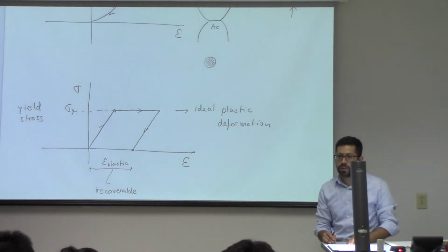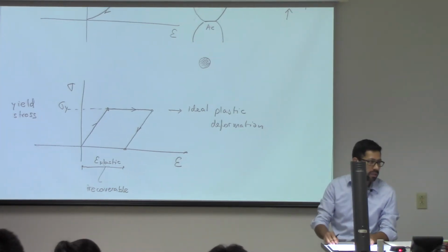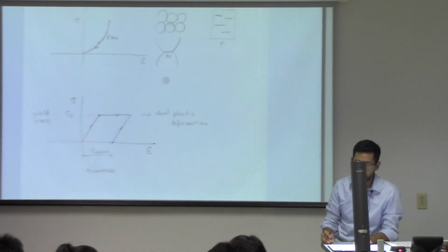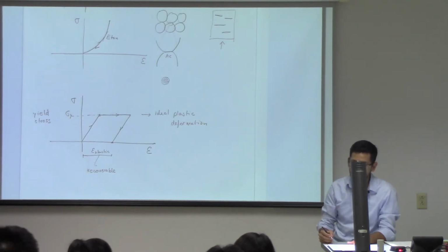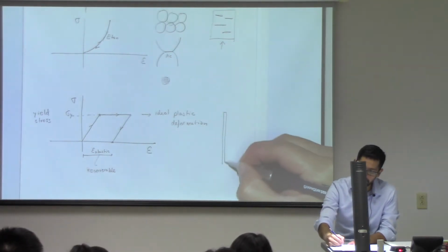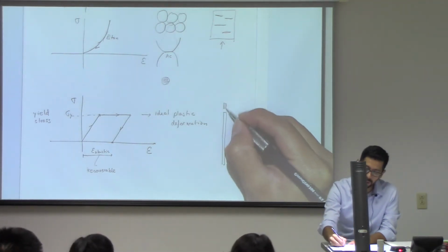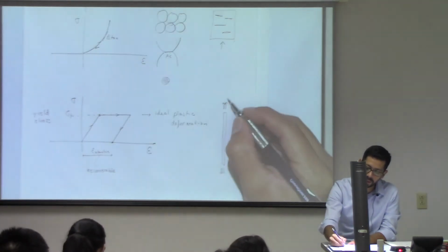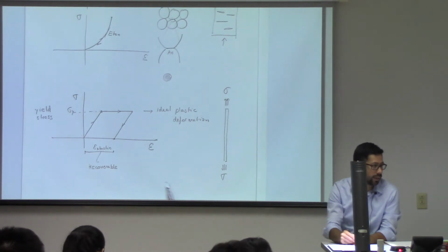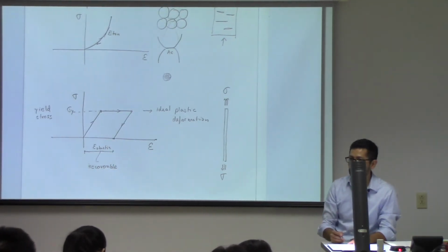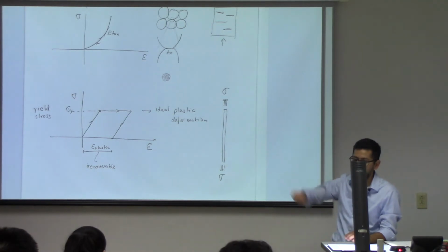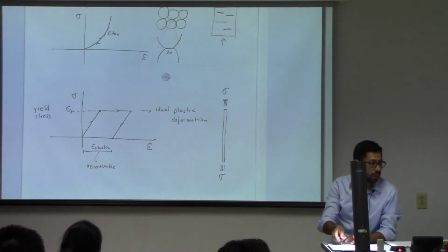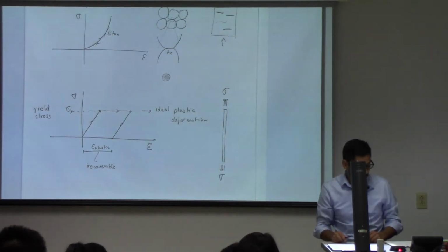Usually, for example, I'm positive that you have seen this before in a material class. If you were to test the yield strength of steel, what you would do is you grab a rod of steel, then you put a force or a stress on that bar, and you pull until you get to a maximum value. That maximum value where there is no more linearity between stress and strain, that's what is called the yield stress. We're going to come back to this example of steel in a minute.